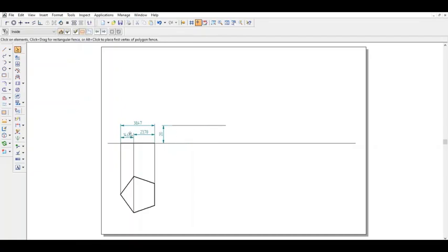So what I'll do is, this particular length I know is 38.47. From this particular point I'll draw a line of 38.47. I know the length, I don't know the angle, but I can draw the line till the 20 mm line, which is above HP. Just draw it there. Now this particular thing is 0.5. But I know that I have to divide this into two parts.